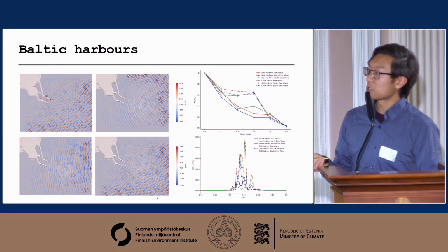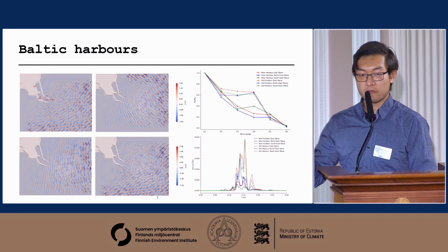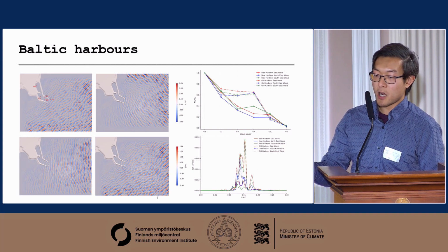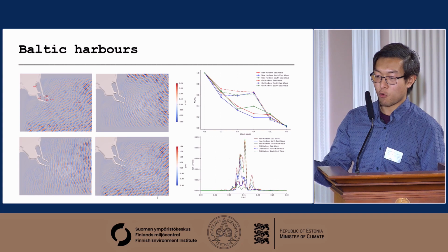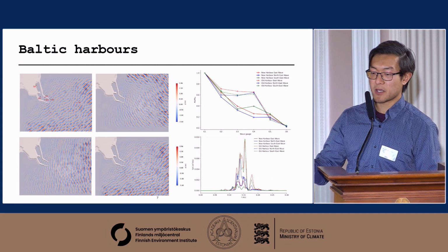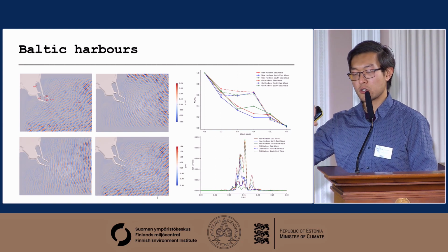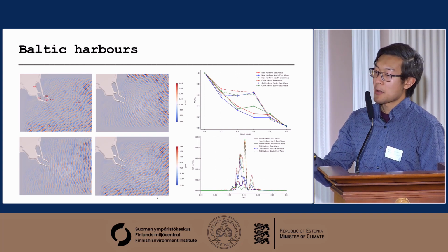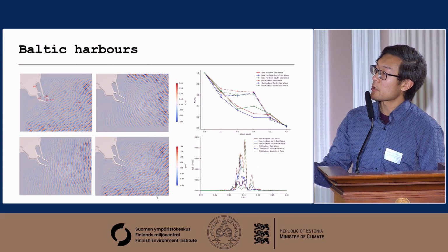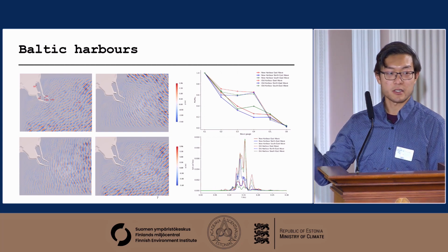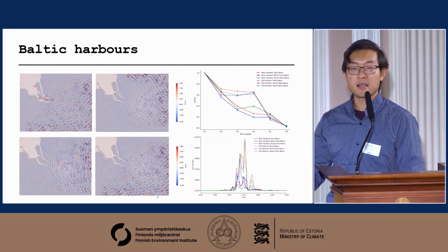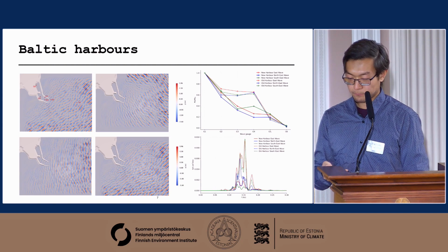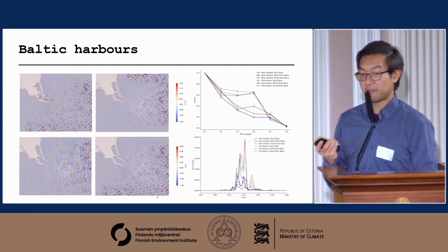But also we can look at how the spectrum, or how the wave energy, is distributing over different frequencies. You can see in the old harbor, shown as dashed line, in the inner harbor area, you have 1, 2, 3, 4 peaks, or almost 5 peaks. So due to the wave interaction and transformation, you have like a 5-mode wave condition in the old harbor layout. But in the new harbor layout, in the inner harbor, you have only 2 predominant peaks. So that actually makes it easier to design your infrastructure, so we'll consider only 2 primary modes instead of 5 primary modes. So that's one of the studies that we've been doing with FNPF.